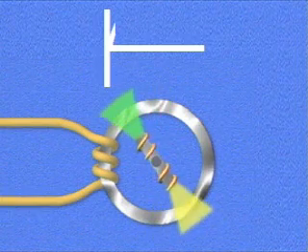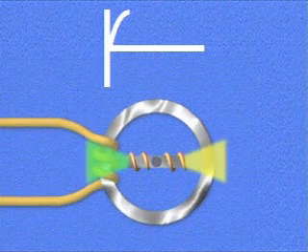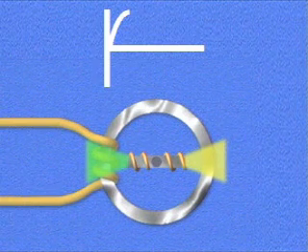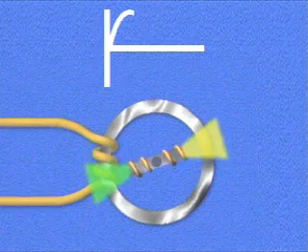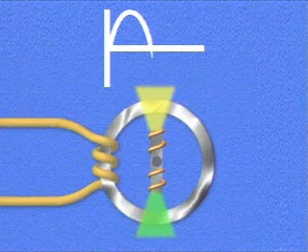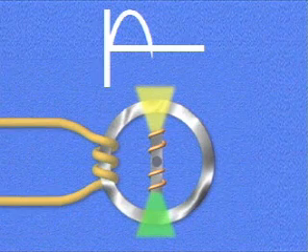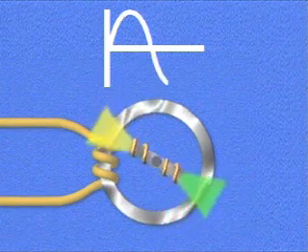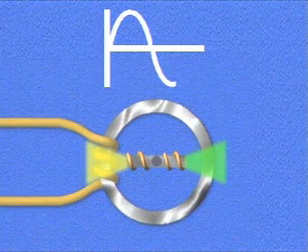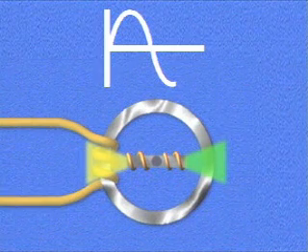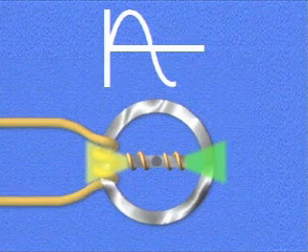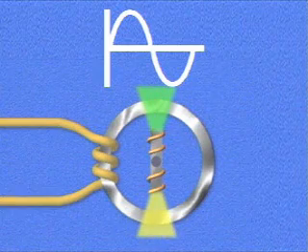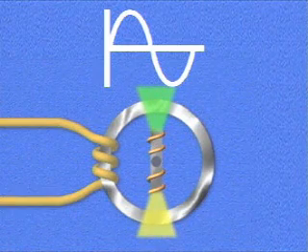Now, as the electromagnet rotates through the first quarter of a complete revolution, the output increases to maximum in the positive direction, and then drops to zero again as the magnet reaches a point 180 degrees from its starting position. As rotation continues, the output reaches maximum in the negative direction as the south pole of the magnetic field crosses the conductor. The output decreases again as the magnetic field moves away from the conductor.